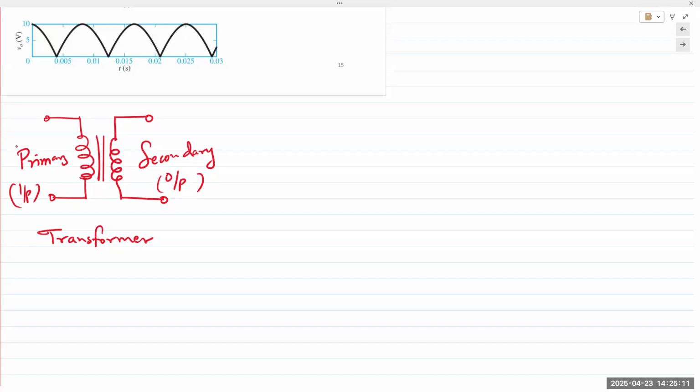When you want to transmit this voltage over long distances, this voltage needs to be stepped up, increased in size. And the transformer is the device that allows us to do this with simple ease. Transformers have interlinked windings. These interlinked windings have a turns ratio. An inductor has a number of turns, N. I'm assuming at least you're familiar with that, perhaps. So the inductor has a quantity known as N. The N is basically the number of turns that the coil has.